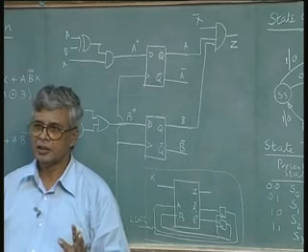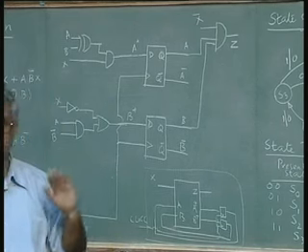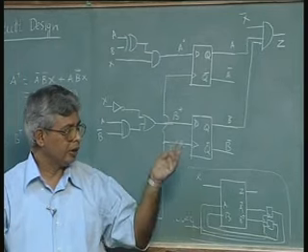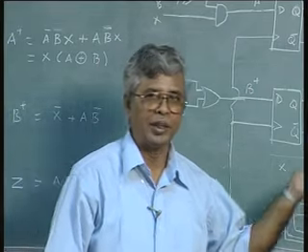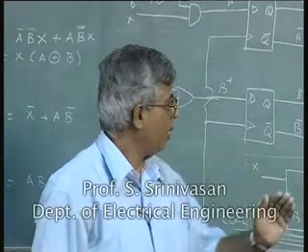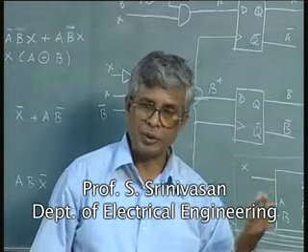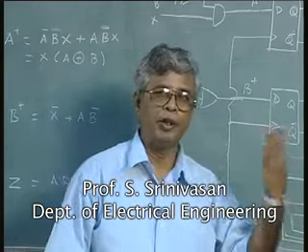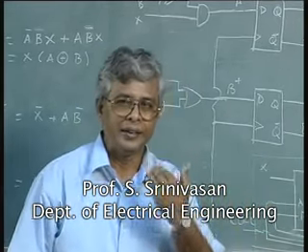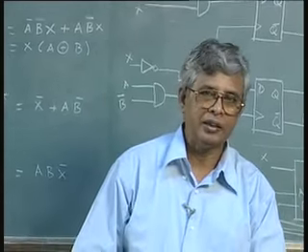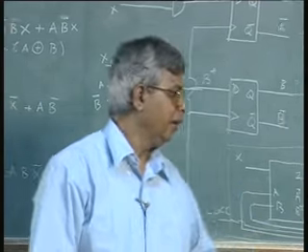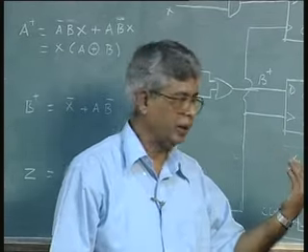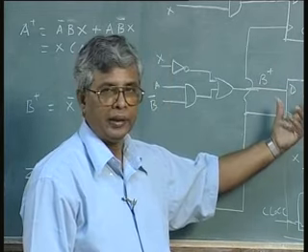From the specification you draw the state graph, from the state graph you go to the state table, from the state table to the transition table. The transition table you map into hardware. There are options for hardware, this is only a simple gate oriented option. Combinational logic can be implemented using multiplexers, programmable logic devices, and many other ways. Whatever choice you want to make, you make that choice and implement it.